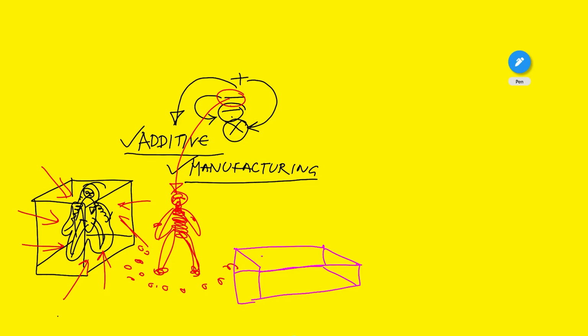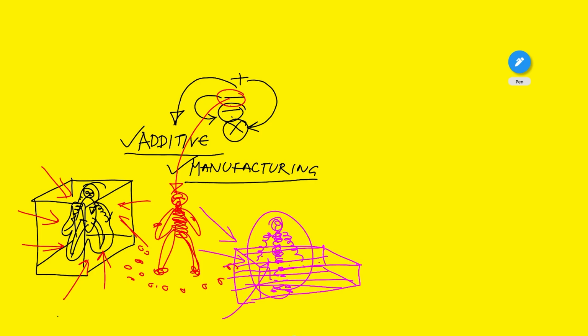So there is this polymer bath which has a polymer in a liquid form under controlled temperature and conditions. I put a heat or a device like a laser and I build layer by layer my entire Iron Man model. This comes out clean, emerging from the bath or liquid without any wastage. The remaining liquid is recycled for the next batch.